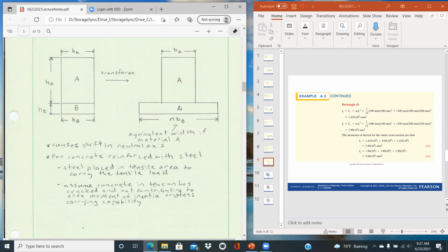when you're looking at a roadway, as trucks are driving over, that's placing a load down. So the lower portion of the concrete would be in tension, whereas the top of the road surface would be in compression. And so concrete is a brittle material, and it's able to withstand compressive loadings well, but not tensile loadings.